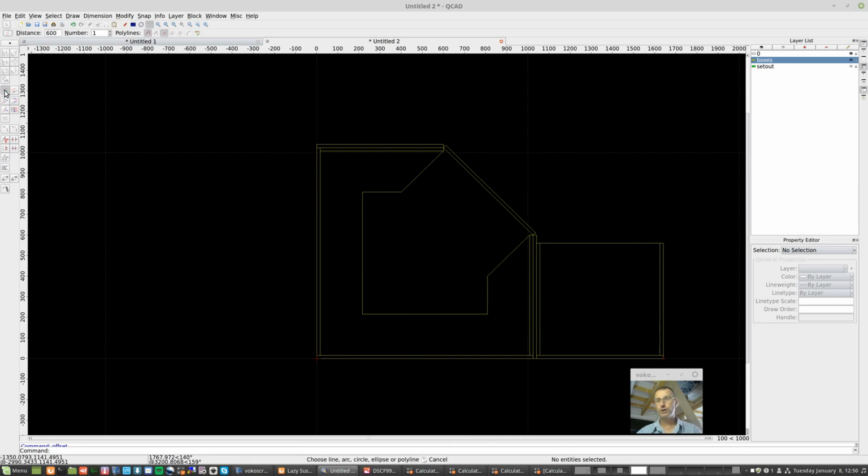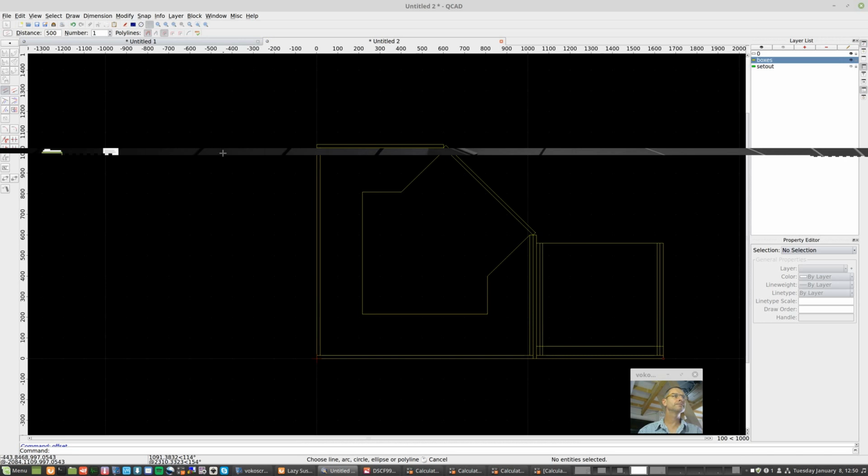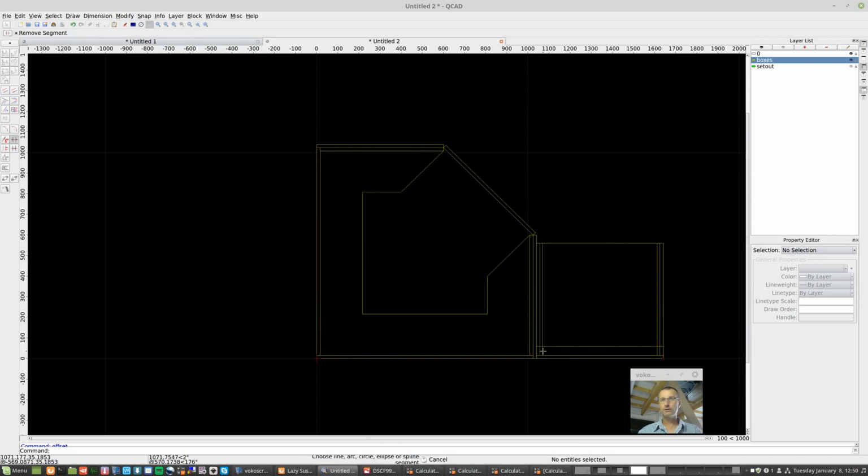Then we need, with the runners I use, if you look on other things in my video channel, you'll see I use a certain type of runner, and they are the most efficient for volume by a mile, much more efficient than the other designs you might have seen around. So the runners have a thickness of 13mm both sides. Then we go back, we need to go 500mm front to back. So on this cabinet design, that's how deep the drawer box itself can be. Get rid of that so it makes sense. And that's basically dictated by the actual drawer itself.